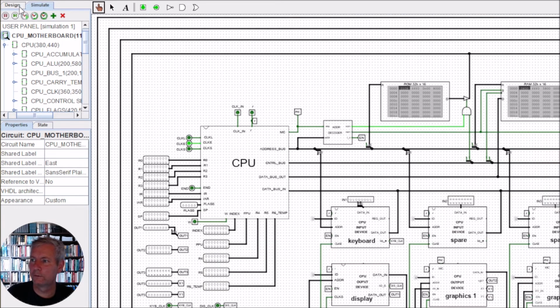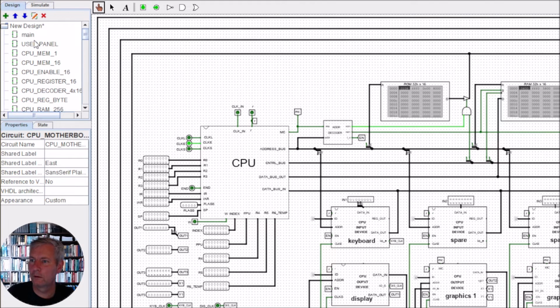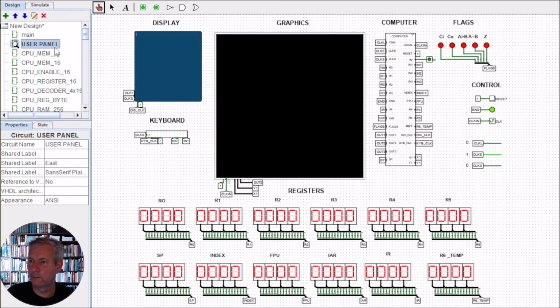So if we go to the top level, now that's the right side, that's good. We've got the letter A sitting in here. Now when I count through here, remember we're going to go to the ROM and it's going to set up the stack pointer first of all, and then it's going to go over to the beginning of the program. So I'll just count my way through here. You can see that the stack pointer has been set.